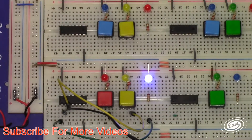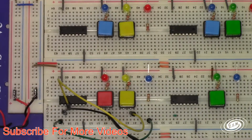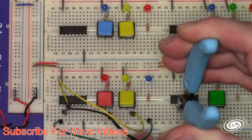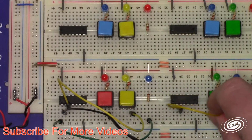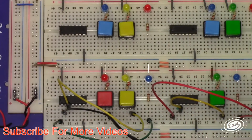So now we're going to look at this one over here. This is going to be the inverter. Now for the inverter, I tied... well, that's not right. So I need to tie input 2 and 3 together, and that is going to go to my switch. And then pin 1 is my output. That will go to my LED.